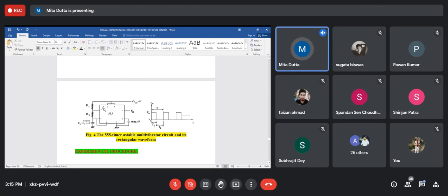Since this is an actual experimental procedure, this actual capacitance which is Cx, in theory is written as C test. Here we have a fringing effect and parasitic capacitance present, so the Cx is not linearly proportional.